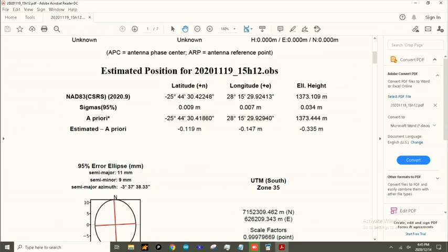In this video we will be showing you our working configuration for our NTRIP Caster or base station, where we have a very accurate position of the antenna already established, as discussed and explained in the first video of the series. From that we will be configuring our GNSS receiver, the different flags and all the data messages that we need, and how we're going to transmit that data stream with its corrections to a server on the internet. From there we can take those corrections and deploy them to our rover or NTRIP client in the field to get up to 14mm accurate geolocation services.